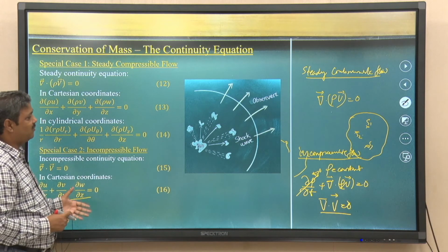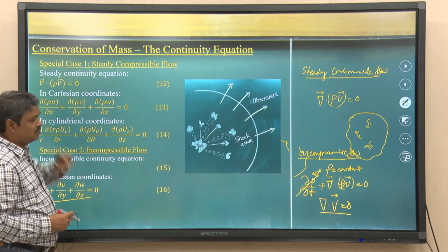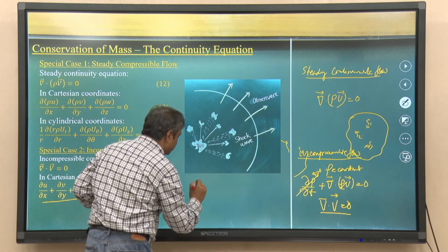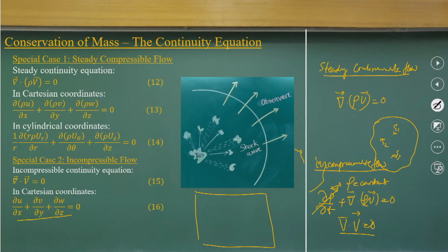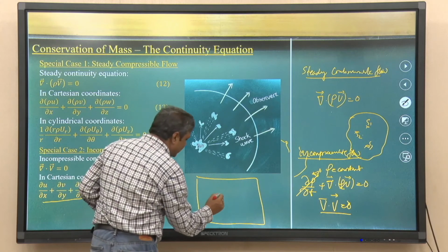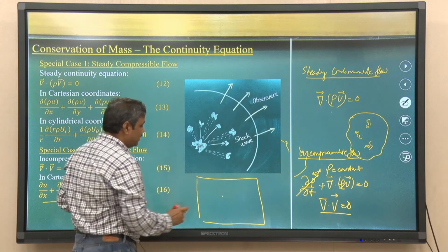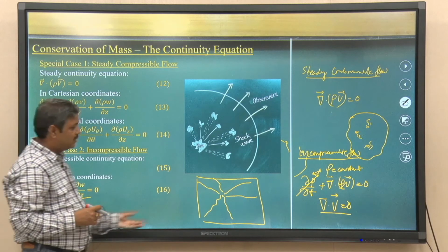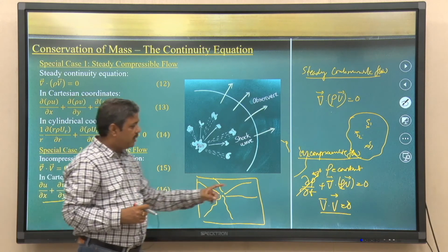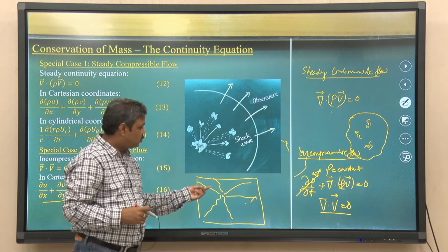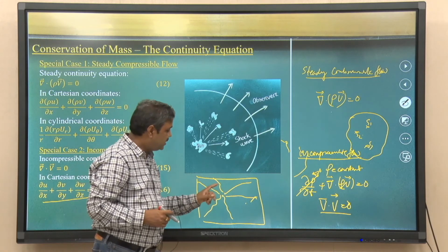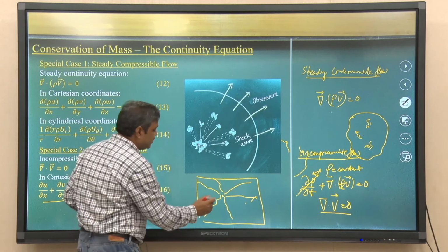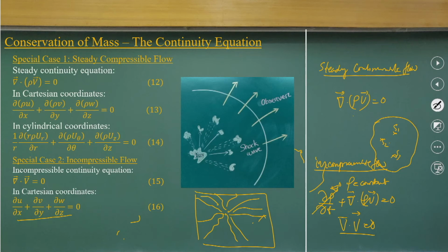Now, let us interpret what actually happens for incompressible and compressible flow. Without regard to steady or unsteady behavior, that does not matter. If it is an incompressible flow, which is what we encounter most of the time, and there is any change in the velocity field, that will propagate instantly throughout the domain. I am just repeating it. Since there is no time component here, even if it is an unsteady flow, any change of the velocity field will affect the whole domain.